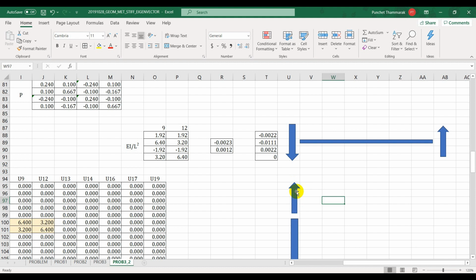Gets pulled up. You push your structure to the right hand side, then the overturning moment will pull the column upward. The issue is that you will have the additional axial force coming into your column.